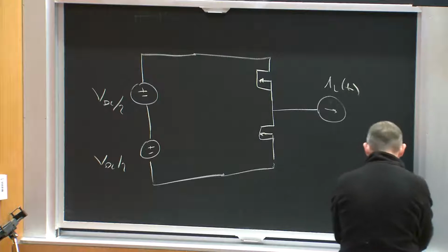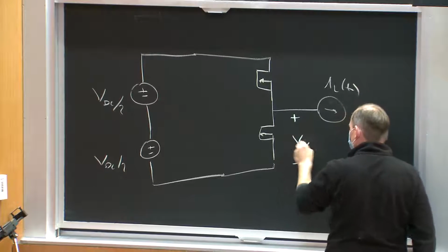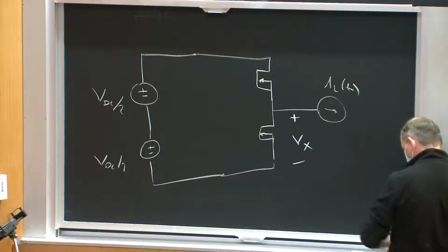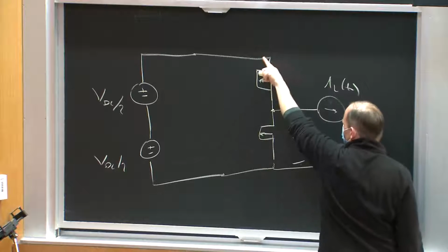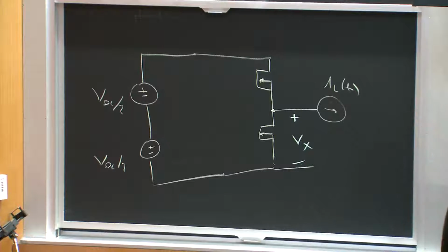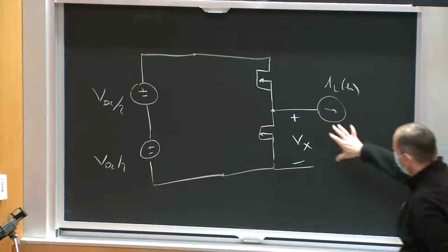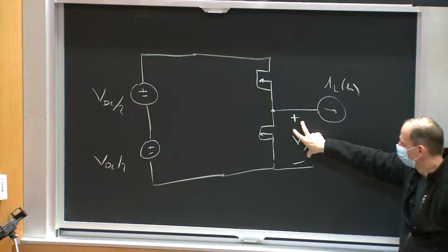And my goal is to basically generate this voltage Vx according to some command, right? I either want to make VDC or 0. I want to make Vx go to VDC over 0, right? I want to use standard motor drive techniques. I don't want to deal with all this funny behavior. And yet, maybe I would like to reduce the slope, the slew rate of Vx.